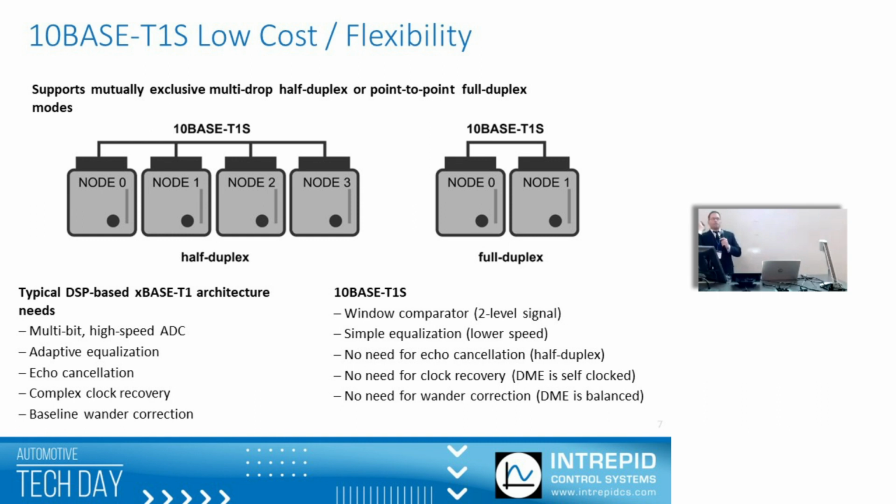The only difference between standard Ethernet and this newer form of Ethernet that's a bus topology is that when a transmitter transmits something on the network, all receivers will receive that. The receiver receives a message and it can inspect the destination MAC address. Is this for me? Yes, I'll consume it. Is it not for me? Then I'll just ignore it. So the decisions about what happens to the individual frames happen in the media access controller, the MAC, of the individual nodes. But they're all connected to the same network, the same 2 wires, and they'll all receive the messages at the PHY level.